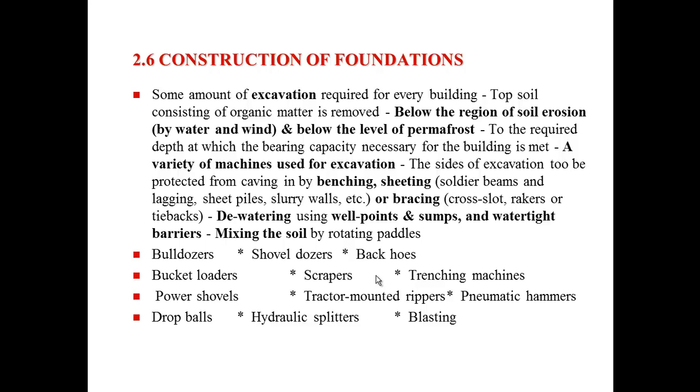Some excavation requirements for every building. Topsoil organic matter must be removed. We generally set this material aside because it's valuable in our landscaping later on. The required depth, the type of machinery now that we're looking at to get in there. And we look at excavation must be protected from caving in. And we do that with either benching the soil, or sheeting, putting soldier beams and lagging and sheet piles and slurry walls, or some type of bracing where we've got rakers and tiebacks, and we'll look at some illustrations of those.